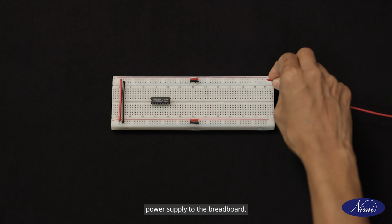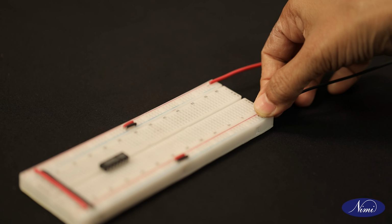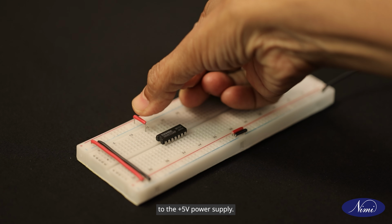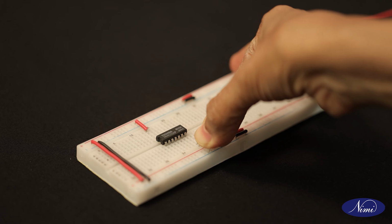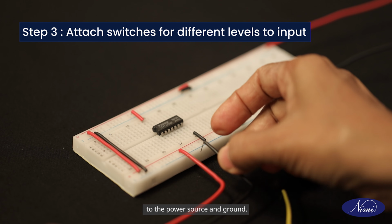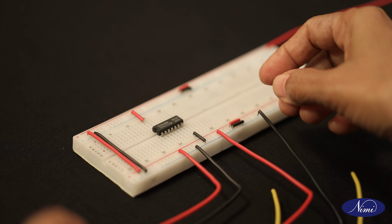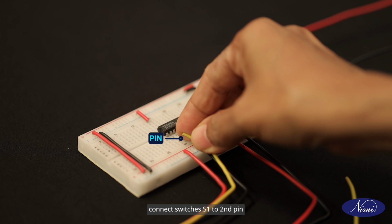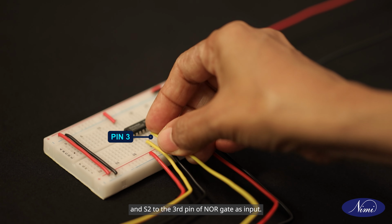Connect linking wires from the power supply to the breadboard. Next, connect 14th pin of the IC to the plus 5-volt power supply. Then make sure pin 7 is connected with the ground. Moving on to the inputs, connect both terminals of the toggle switches to the power source and ground. And connect switches S1 to second pin and S2 to the third pin of the NOR gate as input.